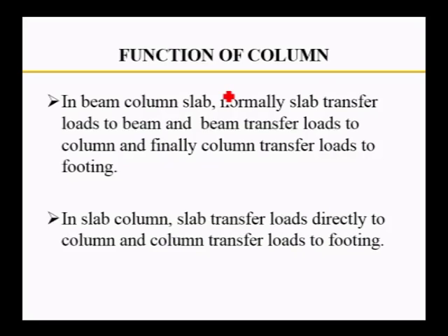What is the function of the column? If a column is connected with a beam and slab, then normally the slab transfers load to the beam. First the slab will transfer the load to the beam, then the beam transfers the load to the column, and finally the column transfers the load to the footing. This is the frame structure.